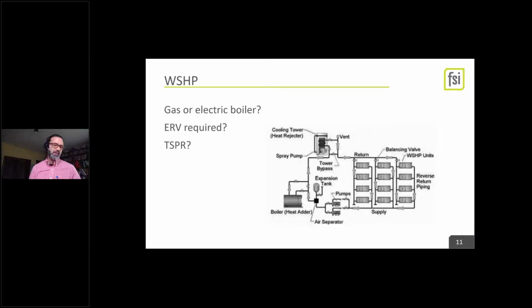And it uses a 2-pipe supply and return. When it's running in heating, it might go all the way to 90 or 100 degrees maximum on the loop temp. So it's really good for heat pump chillers. We'll talk more about that in a minute.